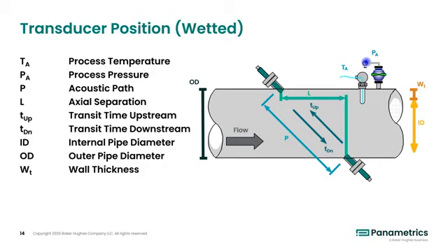One thing to note is that this is the actual volumetric flow rate. For many customers, actual volumetric flow is sufficient. It may be in liters per minute or gallons per hour, but this would be sufficient for many applications. For customers who have processes that tend to change significantly in densities and volumes based on pressure or temperature, we can also take those parameters as inputs into our flow meter and compensate those for a standard volumetric flow.